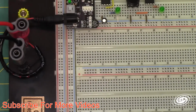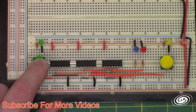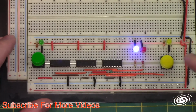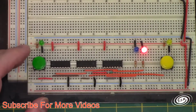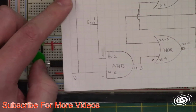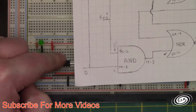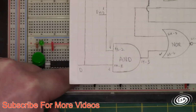So I have this as my D right here, and turn the power on. So this is my D right here, it's my data, and my enable is over here. This is Q and this is Q not. So it's reset right now. So I have a data pin going to pin 1A of the inverter, and also to pin 1 of the first AND gate.